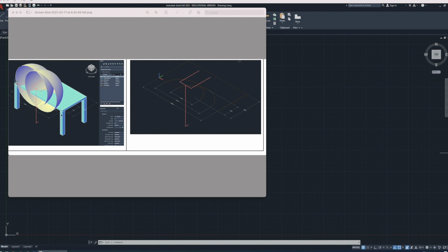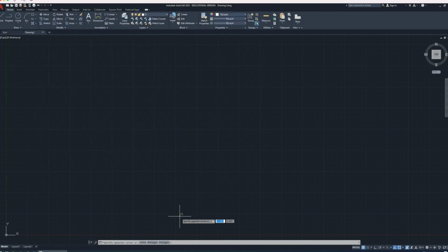And we're going to construct hemispheres representing how far this worker can reach in space around their shoulders without bending or twisting. We're then going to find the intersection of these hemispheres with a workbench top to show how far they could actually reach and touch something on the surface of the workbench without bending or twisting. And we'll add some dimensions to it. We're going to use AutoCAD to create this model.